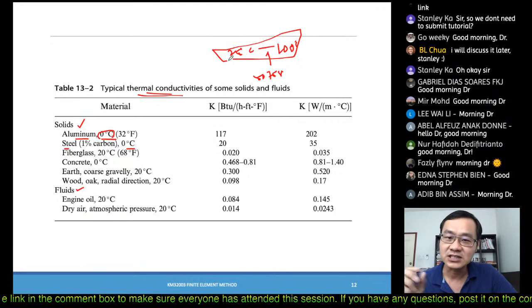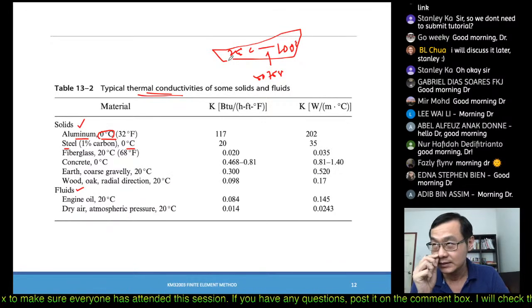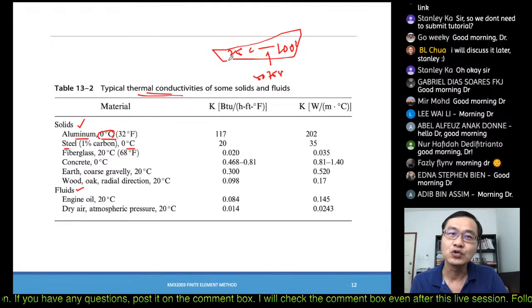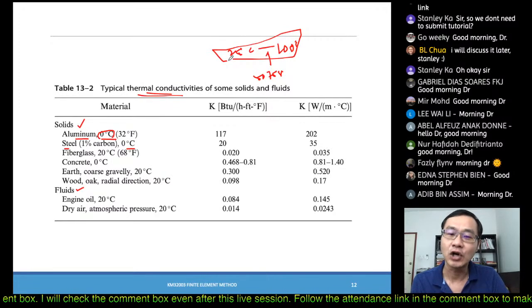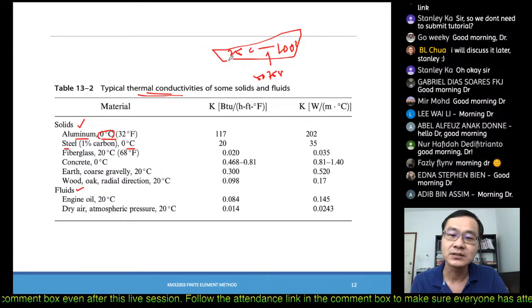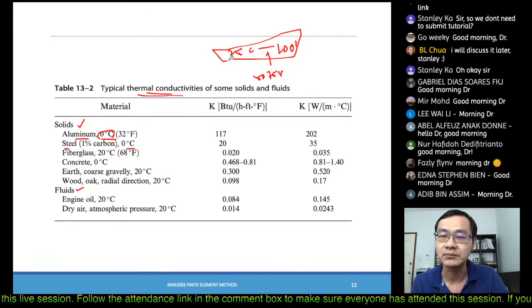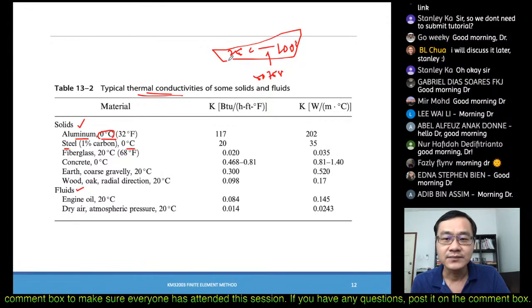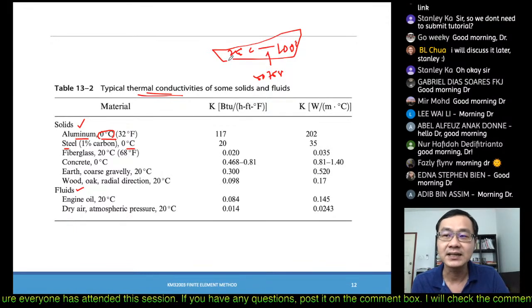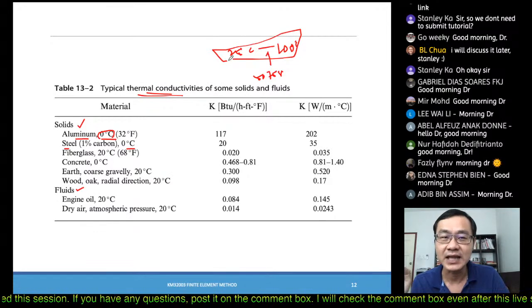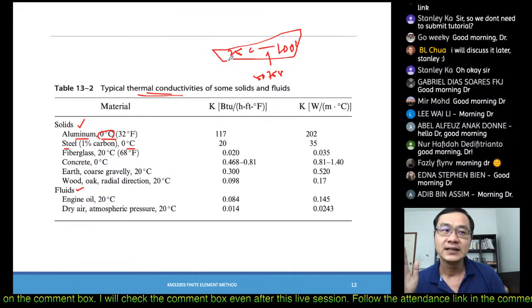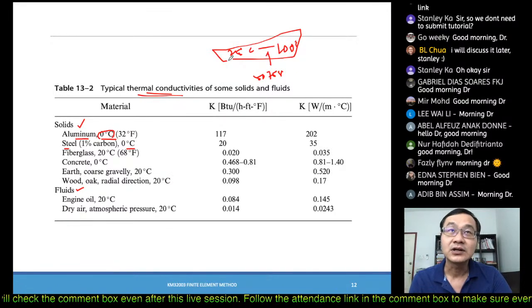When there is that high a range of temperature, it would be better that you find temperature dependent thermal conductivity, meaning the thermal conductivity will change according to temperature. Commercial software allows you to put in temperature dependent thermal conductivity, and in between they will interpolate the thermal conductivity.